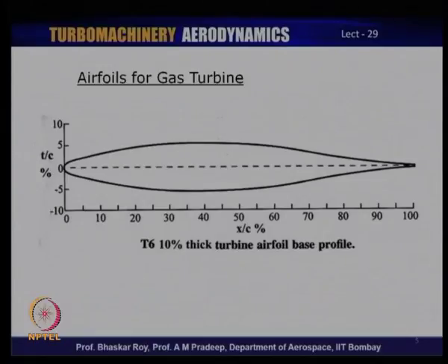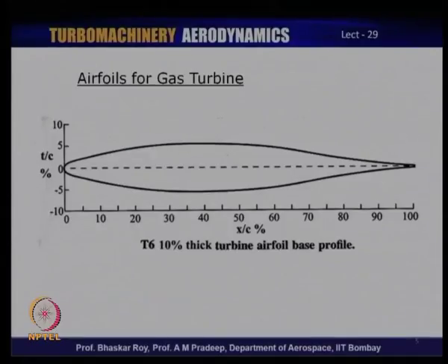This T6 profile, there is another famous one, T106, which is normally used in low pressure turbine, and T6 is normally used in high pressure turbine. Now, this profile is a symmetrical profile, as you are looking at.